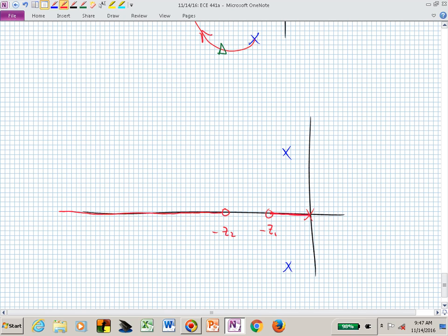And now what do I do? What's my pole zero excess? One. I've changed basically the relative degree of my system, haven't I? Or my pole zero excess by putting 2 zeros in with 1 pole.